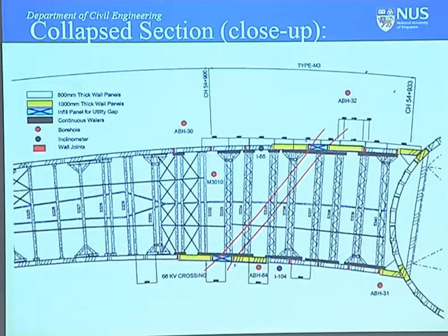So there was a gap there, which, in hindsight, I think is not a good move to solve. Just leave the gap there. I think people should do something like a grouted soil block to at least make sure the gap is filled up. They tried to fill up the gap as they went down by patching it up with shotcrete and some steel reinforcing. But I think it's a really bad, poor attempt.